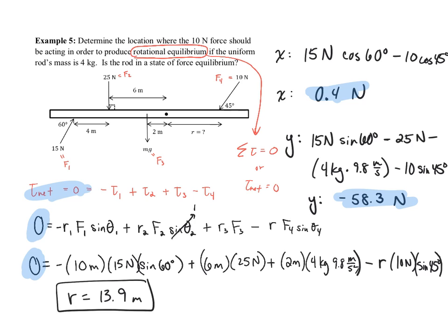It'll do what's called shearing. We'll learn more about that next year, and if you take the engineering course, it's shear stress. Shearing occurs a lot. When a bolt connects several members together and there's too much force on it, it'll literally just snap in place. So if you want to try that with a wooden pencil, just hold this steady and pull down on the other end. And that's what would happen to this pin if its maximum strength were less than 58.3.